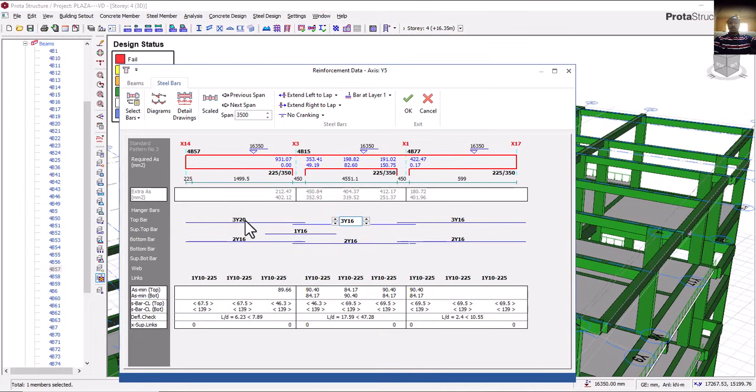All right, if I make this one 3Y16 and it is failing here, that means I'm going to make this one 2. Can you see, even at 2 it's not passing, except if I want to make this one, say, 20. If I make 1, what about 1? 1 is failing. Can you see it now? So it's now your choice that at the support here they are going to be using 2Y20. That's if you want, so that all the top here will be 3Y16. As I said, it's your choice, but the way it is here, I don't want this type.